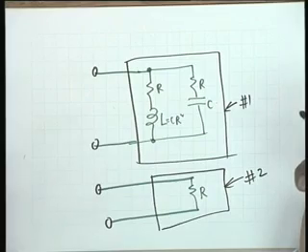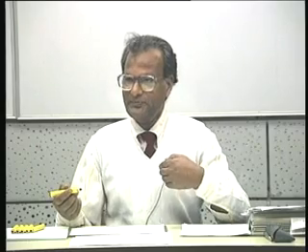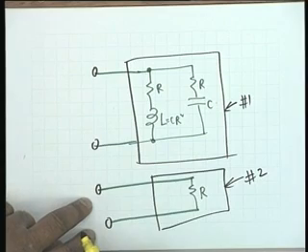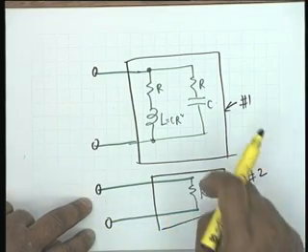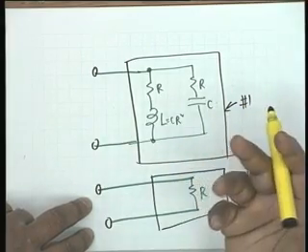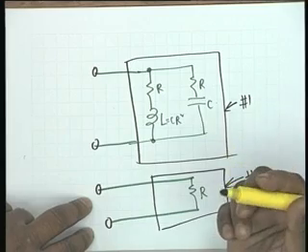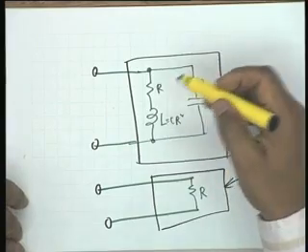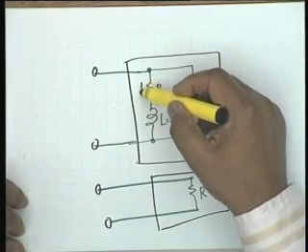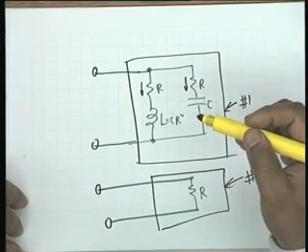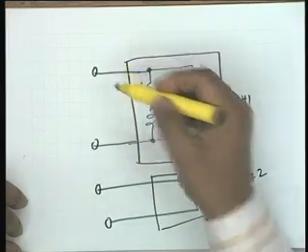This is one of the ways that people try to connect a battery and open it. But as far as external manifestations are concerned, suppose you connect a battery here. The current at 0 minus would be E by R. Alright? At 0 plus, no current. Right? No current. In other words, whatever current flows in this branch, the negative of this must flow in this branch. You understand what I mean? So that the total current here is 0.